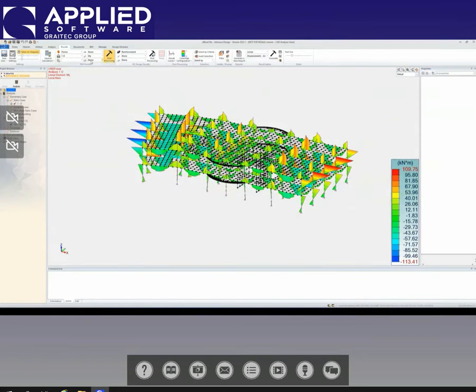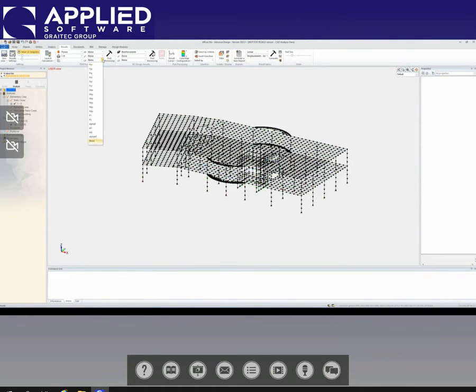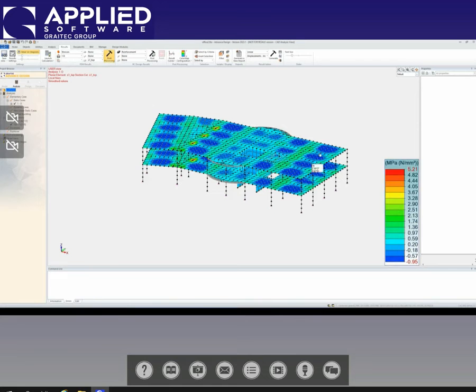So you can simply switch to planar, and here I can have the forces inside the elements. And if I want to see the stresses, you go to stresses, and here you can see all of the related stresses in your planar elements. So for example, if I want to check the S1 top, click there, and this is going to be the stress distribution in my planar elements, as you see there.